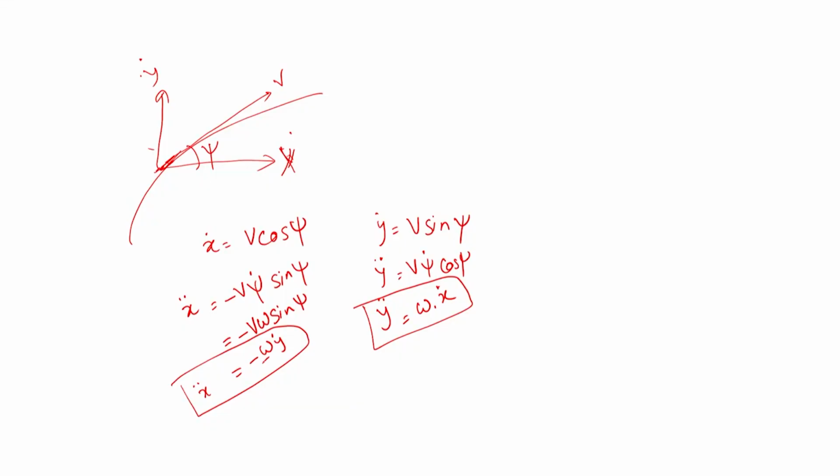Okay. So, here my omega is unknown. Obviously, to model my ignorance, I will provide some white noise here. Again, when I do not know something, I have to put some white noise, because omega is the forcing function. I do not know how my target is maneuvering or how my vehicle has taken a turn, I have no idea. I am sorry guys, I have no clue. So, I have to put some noise here. That is my ignorance about the real world, modeled using some random excitation. I am telling this repeatedly because it will help you understand it physically.